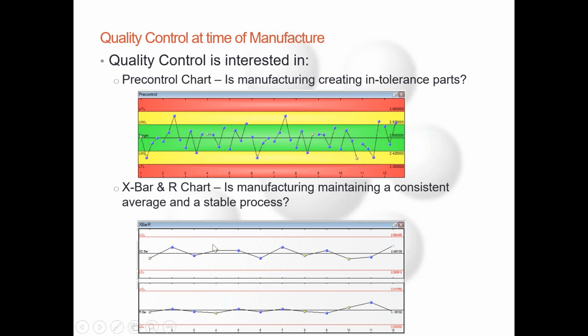How much does, well, actually I should use this one. How much does the data spread from here to where? Roughly halfway up here. And that would be roughly the standard deviation here. This total distance from here to this dotted line is 3 standard deviations away. And this is on the X-bar R chart. Even though the R chart's down here, here's where you could see what your 3 standard deviations is by subtracting this number from that number and dividing by 3. And again, that represents how much variation your data is seeing.